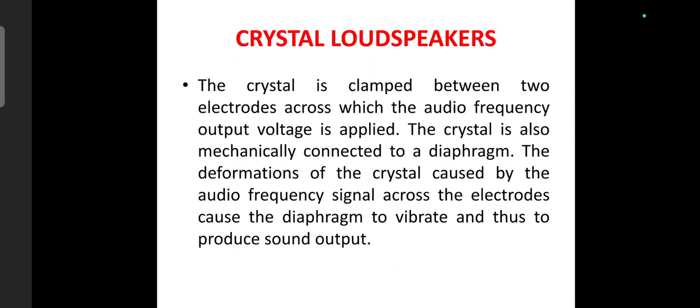A crystal loudspeaker works based on the piezoelectric effect. A piezoelectric crystal is placed between two electrodes. When an audio voltage is applied across the crystal, it expands and contracts slightly. These tiny mechanical movements are transferred to a diaphragm. The diaphragm then vibrates and produces sound waves.